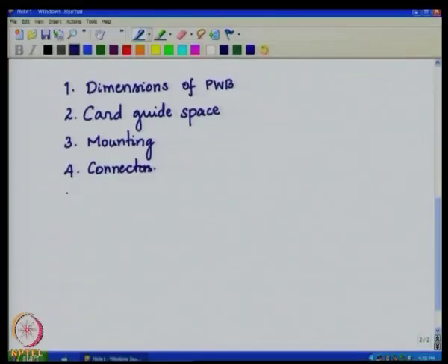Only after you have finished placing all these, you go on to the layout of the components. So, you have to lay out the components, of course, in the order of criticality. When you lay out the components, you do not have a formula for this. It is intuitive. You will learn more and more as you make more and more PCBs.